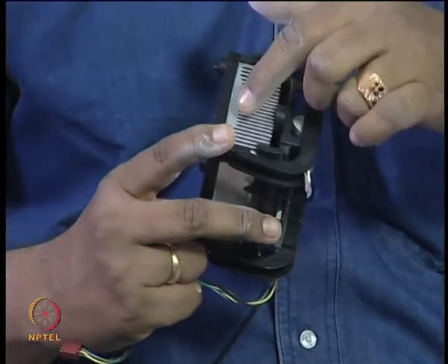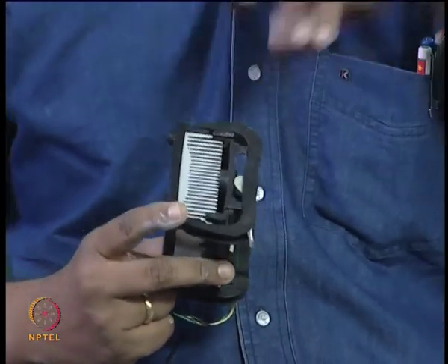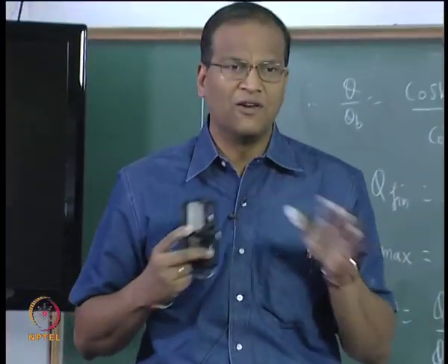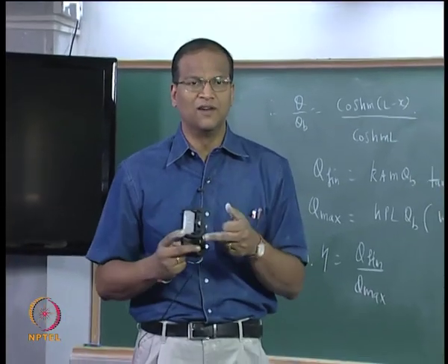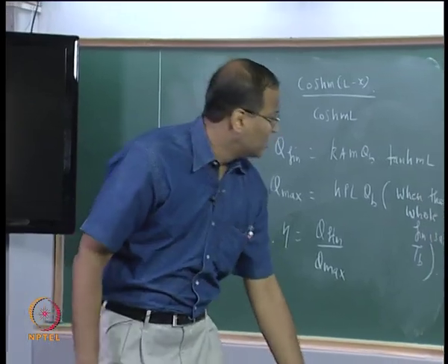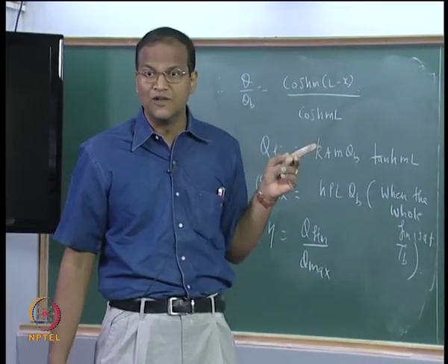Now, you have to find out the heat transfer from the fin divided by the heat transfer without the fin, and if it is not greater than 2 or something, do not add fins, do not add a plastic fin and screw up the heat transfer. Okay. So, this is the effectiveness. This is a performance metric. Now, this should be greater than 1, it is not an efficiency parameter.